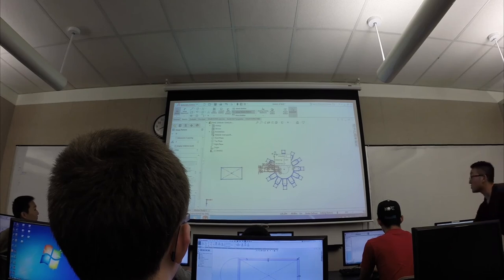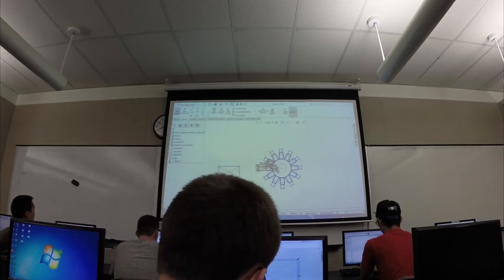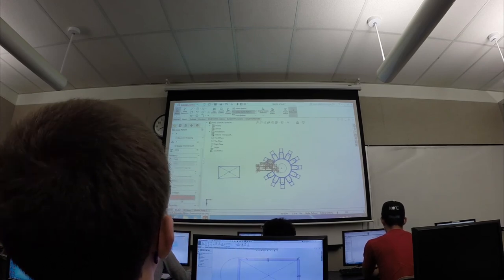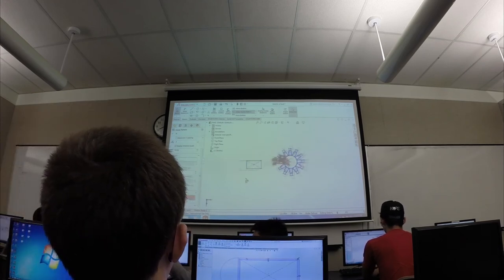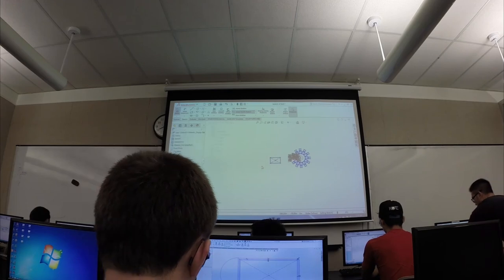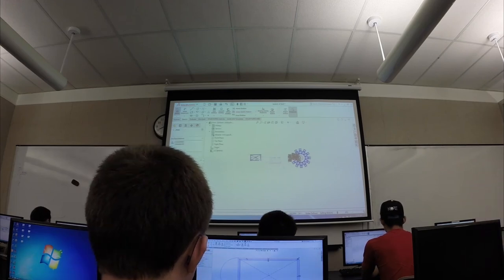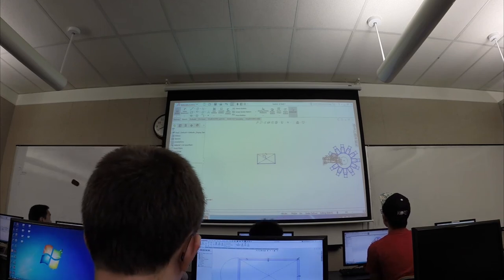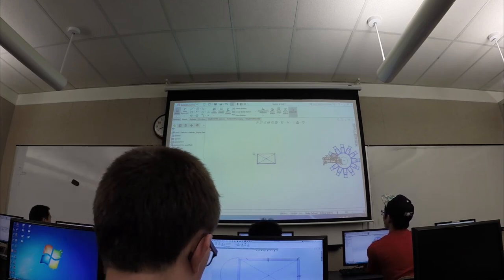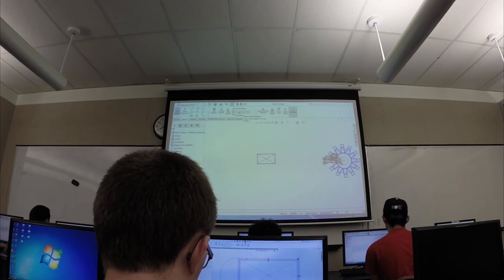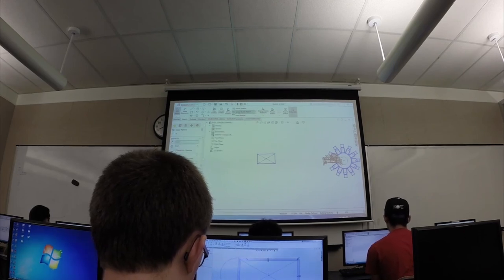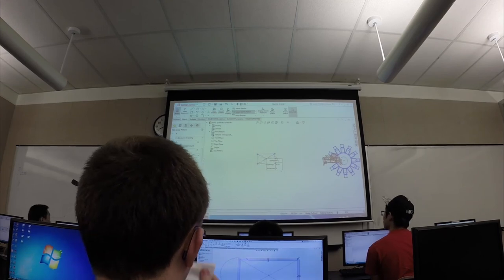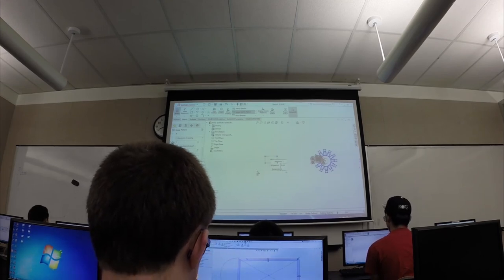Not the most fun thing to do. Alright, actually let's play around with this little rectangle that we might have made earlier. SolidWorks 2016 changed a bit on this. Cool. So in entities to pattern, we're gonna select this box here, right?